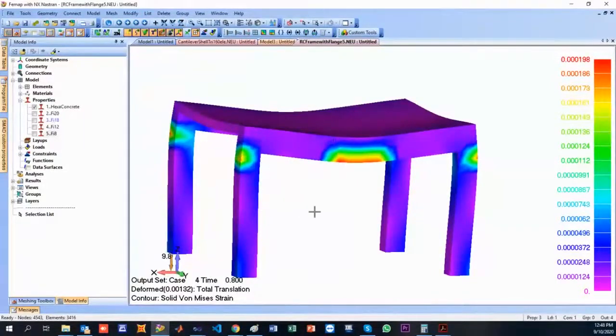Why here and there? Anybody? Cracking, right? Horizon is correct. We have crack development, strain concentration, but why here and there? We reach the maximum tensile or compressive strength. And why did we reach that strength? Because of what? Shear, axial force, bending moment, torsion. Anybody? Max tension due to bending, Stefan says.